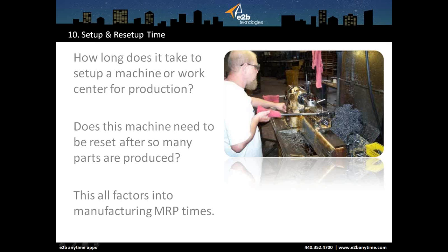You need to understand and have a system where you can define how long it takes me to set up the machine to begin with, and then after how many pieces I need to set it up again, and when I need to reset it up, what's the amount of time it takes me to do a reset up. Again, all of this is going to factor in the lead times for your manufacturing.